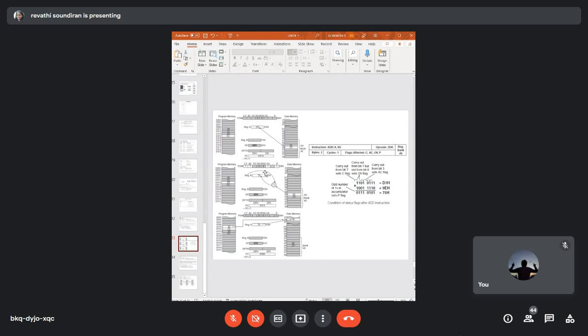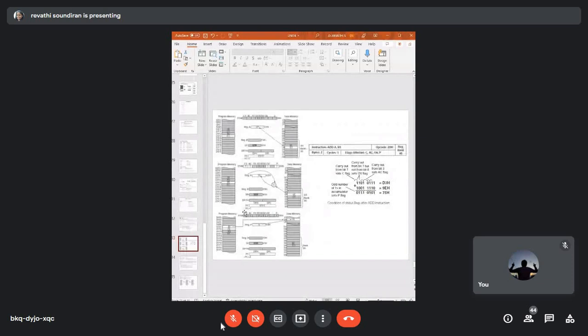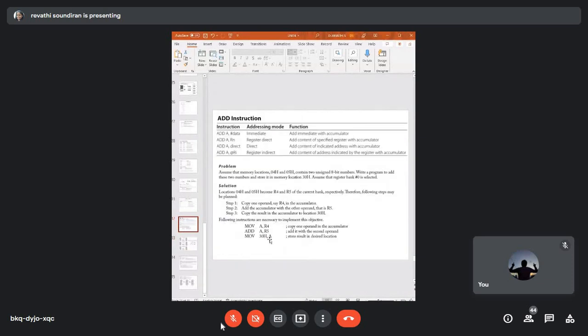Okay, so now you have understood this point. After the addition operation, the number in the accumulator is 5, which is an odd number, so your parity flag is set. So 4 flags typically are altered in the case of an addition operation when you are executing the second instruction.